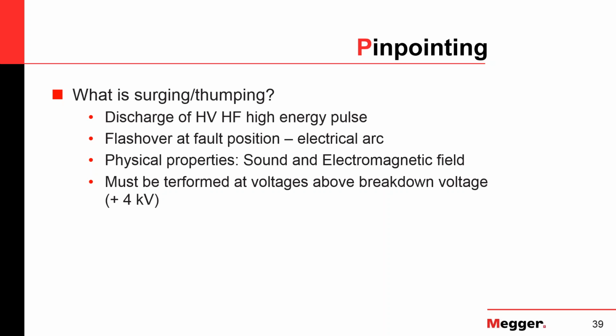While the arc reflection, the pre-location, is filtered, the thumping is done at an unrestricted energy level, so to speak. If you would demonstrate this in air, with a short cable, doing an arc reflection and then a thump, the arc reflection is only a kind of weak sizzling, while the thump is like a gunshot. It's really loud, and it's really powerful.